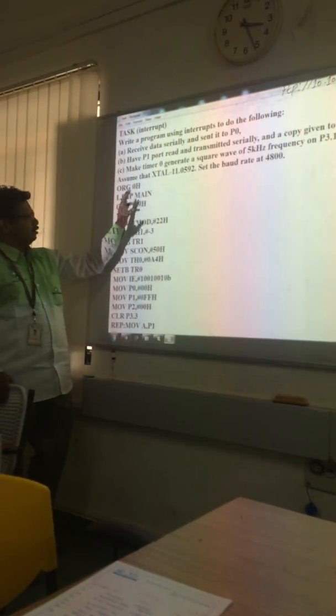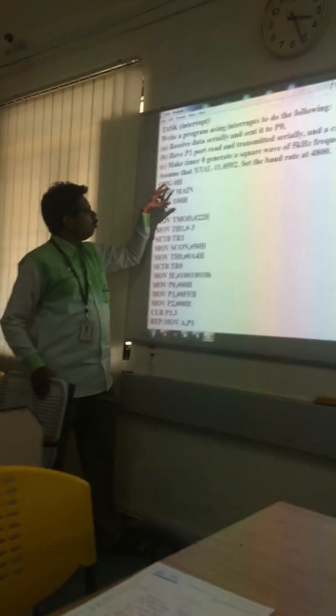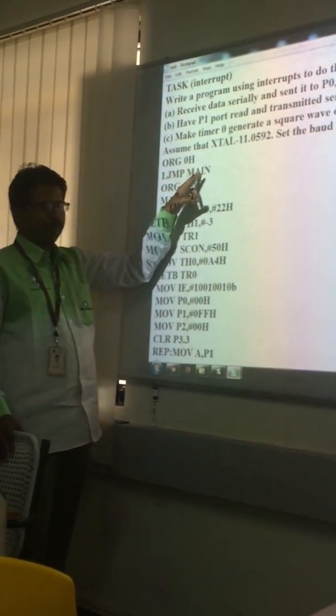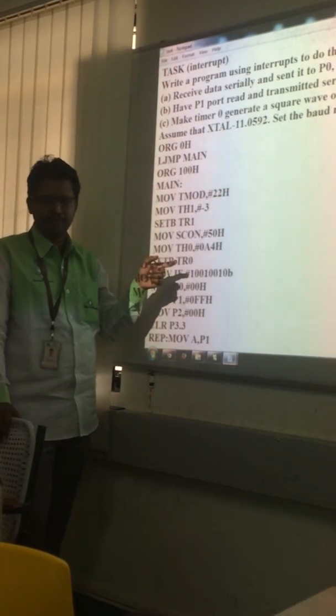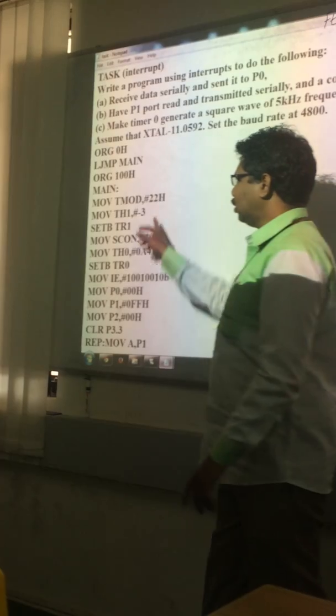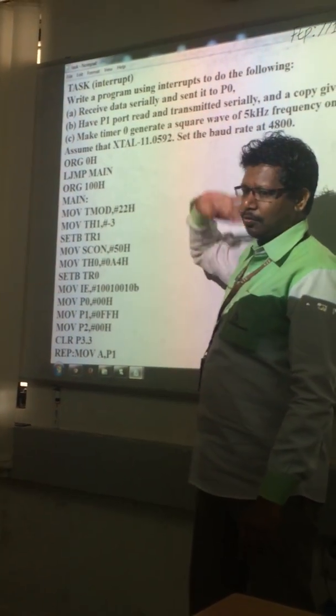Yes, sir. Okay, so now we can start the program. ORG 0, we are going to write this using interrupts, therefore LJMP main. So you have to exclude the interrupt vectors, so we are going for LJMP main. And then ORG 100H, we are going to write the program for main.